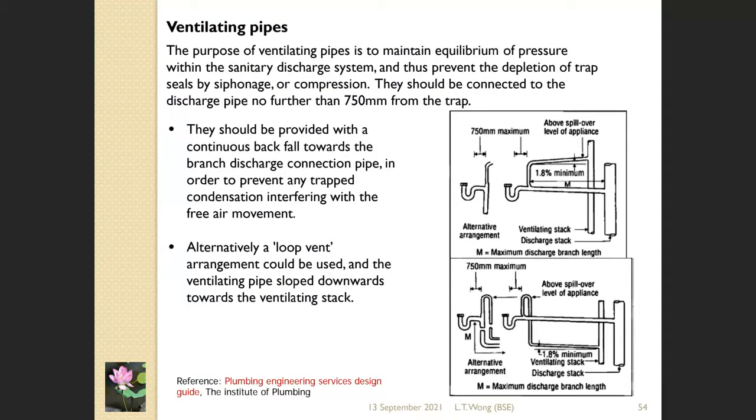For the ventilation pipe connection, there are also limitation requirements, gradient requirements, and size requirements. If all these requirements are followed, the table is applicable. So this is my meaning: the entire set of design has to be applied as a bundle. And this set of design is what I call a pre-calculated design.